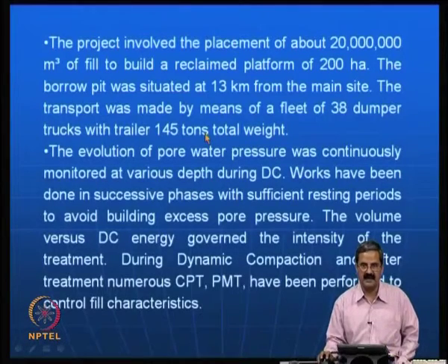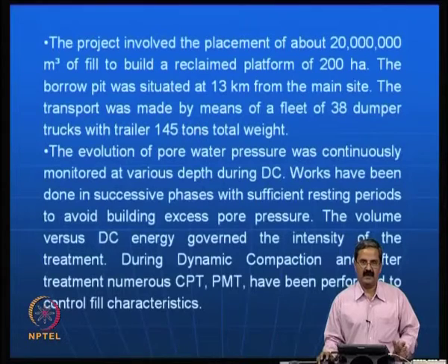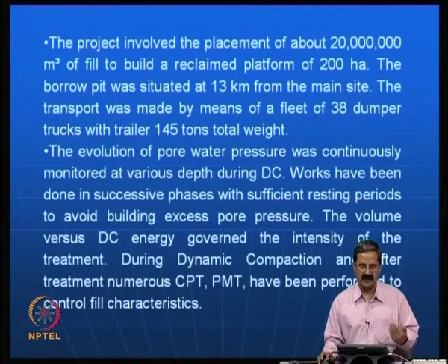You must be able to design even your transportation system very well in a ground improvement project, because you have to get as much material as possible, so that you can start reclaiming and then doing the compaction and recover the soil faster. So this is a big process involved in the planning of operations for dynamic compaction.